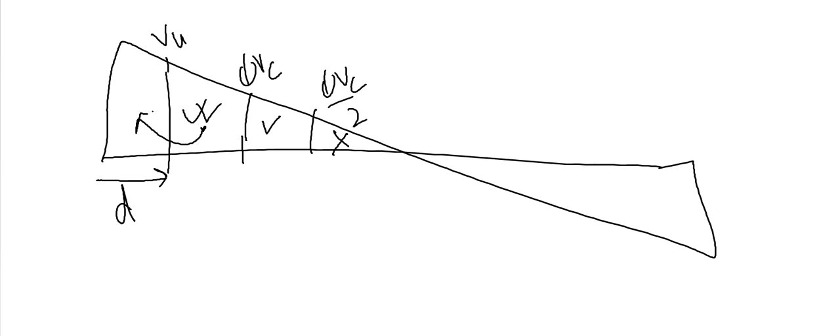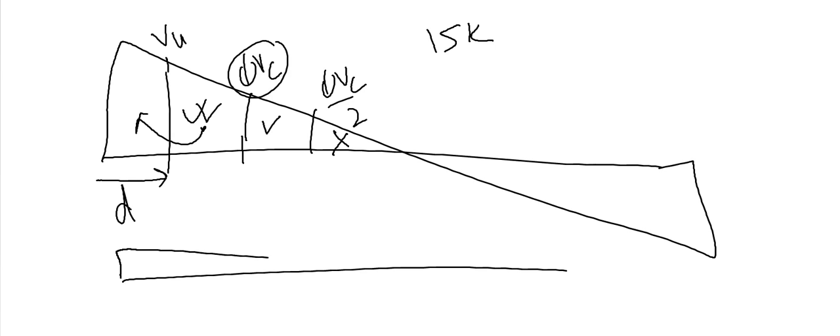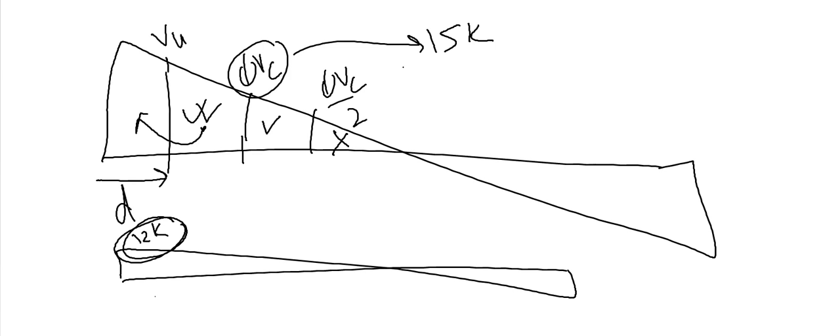Now if, say, this value is 15k, whatever it is, but if you drew your shear force diagram and the maximum value is, say, 12k, then in this maximum shear force 12, this value is 15. Do we need reinforcement? Actually no, but still we should provide up to this.